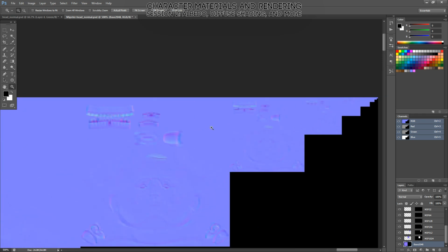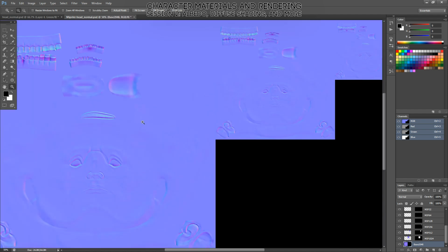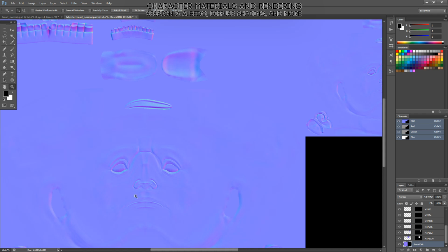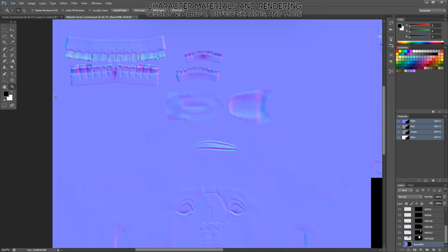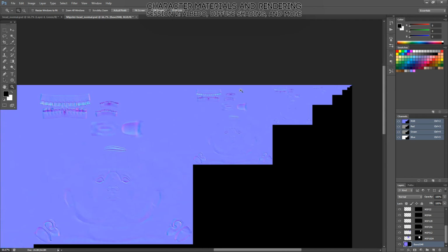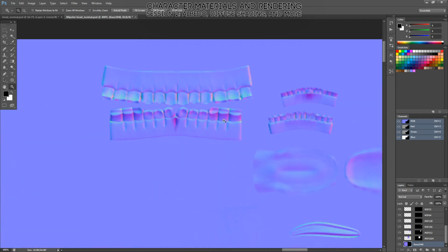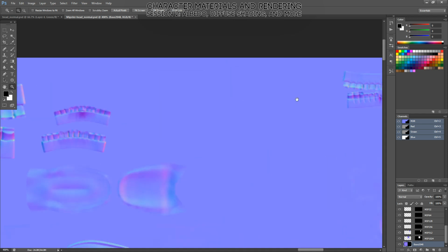So when you're talking about texture sizes, usually the rule of thumb is that if you have a texture that's 2048 by 2048, you would probably want at least 16 pixels between your UV islands, so that as it gets smaller, the texture bleed into these different islands is not apparent.